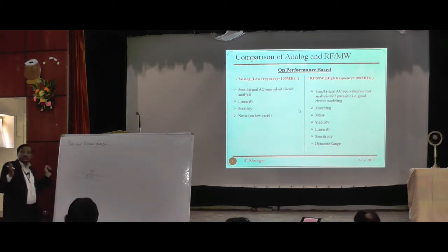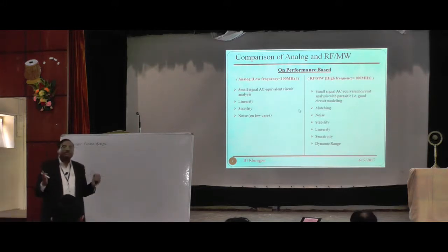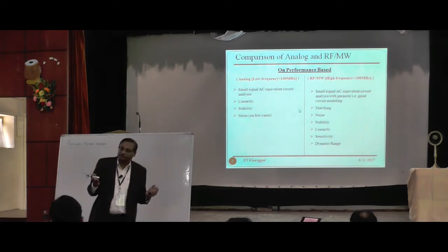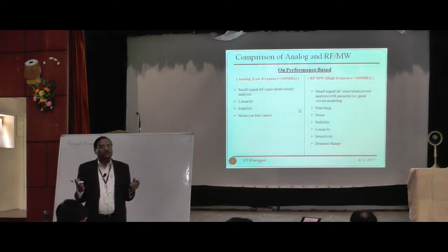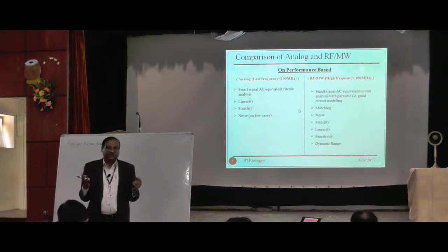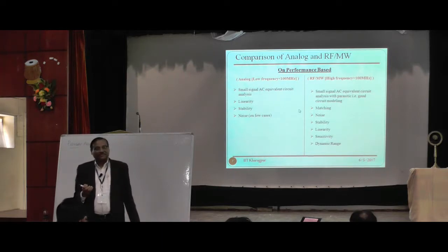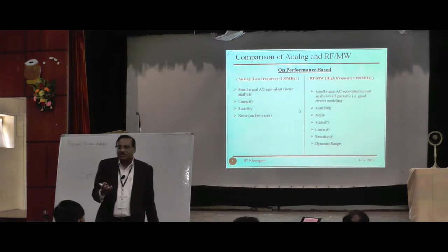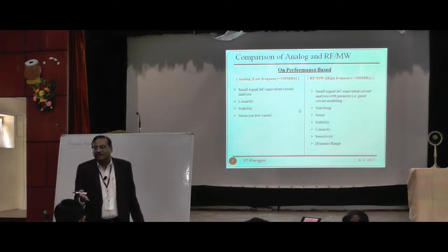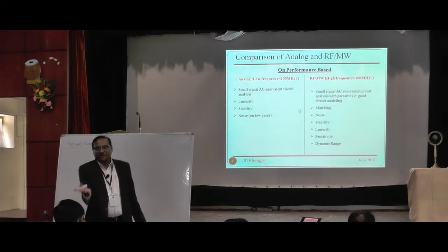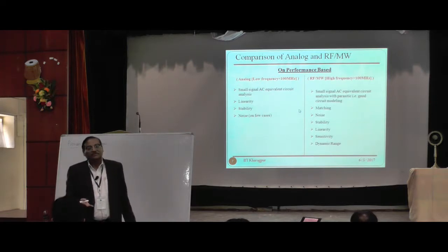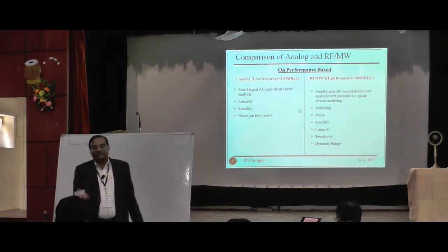We will go into the physical definition of noise later on. But I would say that for any RF system you have to define what the noise floor is. If you don't understand the noise floor, then you won't be able to tell what the minimum signal is. When I say that minus 120 dBm is the noise floor, then I'd be able to detect minus 112 dBm, because minus 112 dBm is above it. It's a negative value, but minus 87 dBm is higher than minus 120.